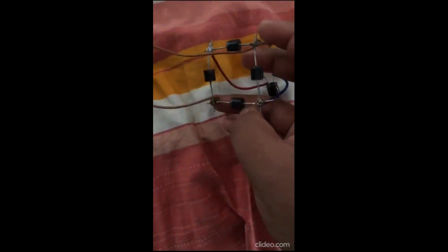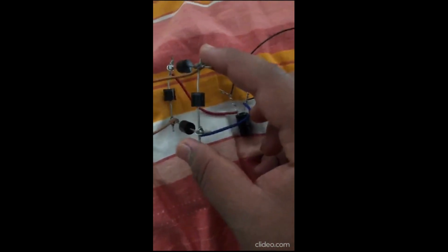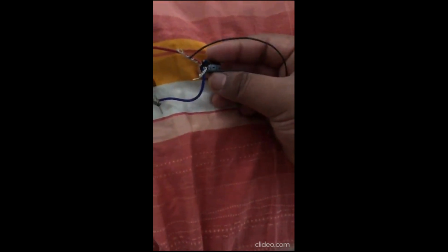And this is a full wave bridge rectifier. This converts the AC voltage into DC voltage, and further this is a capacitor. So this circuit is a setting which converts AC voltage into DC voltage. We lack a multimeter, but if we had one, we could show that there's a stable 12 volt DC current generated.